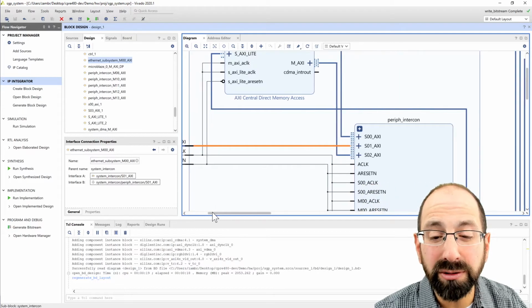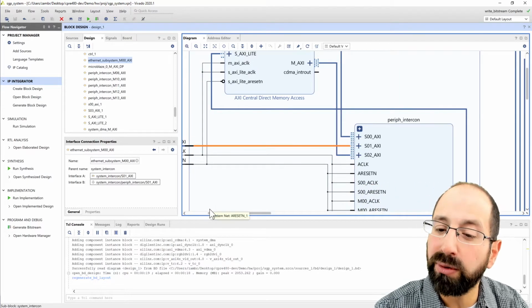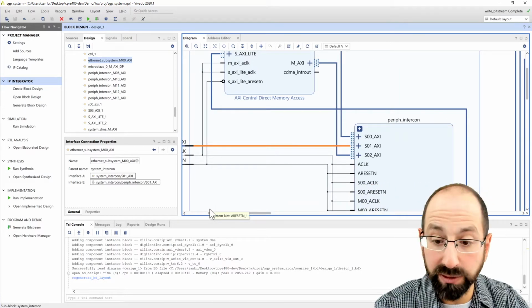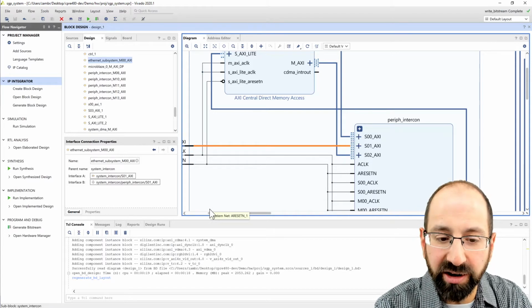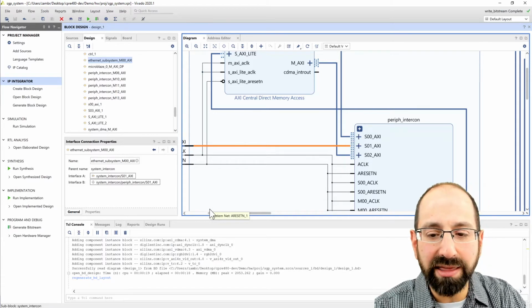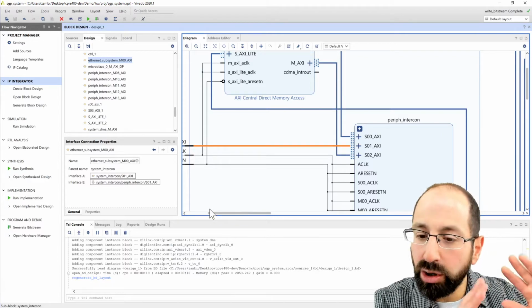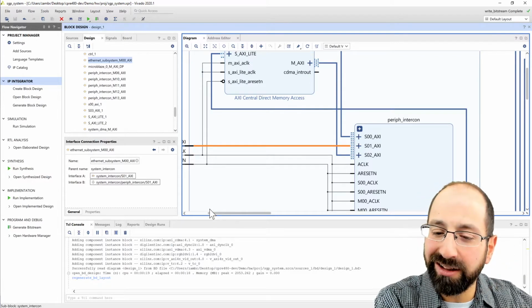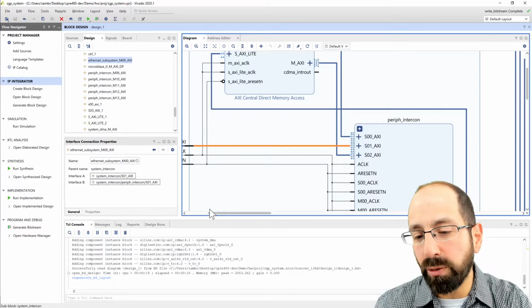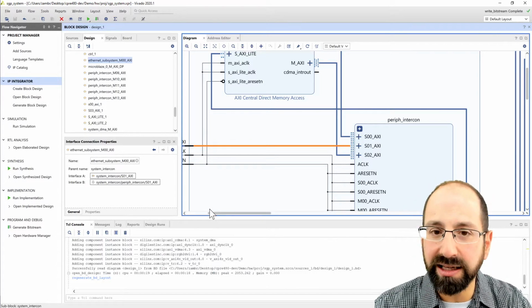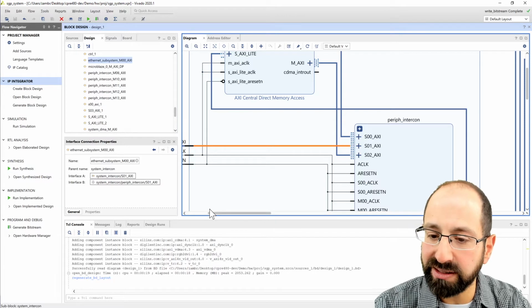It can be useful if we want to write code resident on the board itself to read from the IP cores, to do all the same kind of steps we could do here. We made the design decision early on that we didn't want to be running an operating system on this chip directly, and to go with our workstation running OpenGL, driver sending data over the wire, versus everything being resident in a MicroBlaze processor on the chip itself.